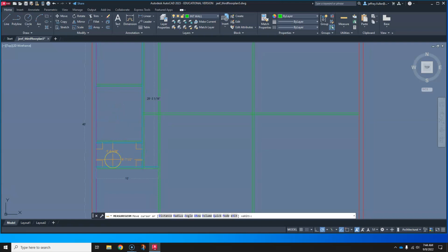And what do we got down here? We've got just enough space for a bathroom. I'm probably going to move this wall just a few inches. So I'm going to select both of those, and then I'm going to click on the Move tool. And I come down here, and I'm just going to grab it anywhere. I'm basically specifying a base point.